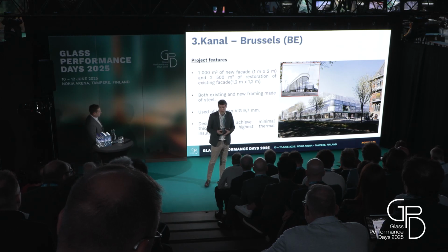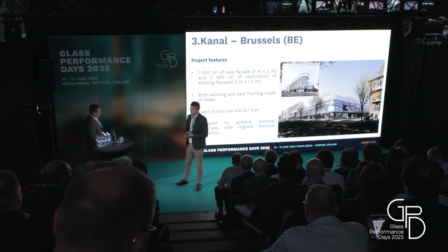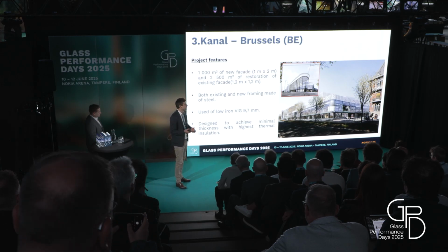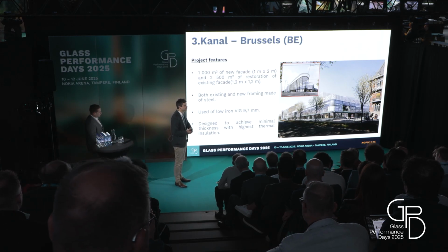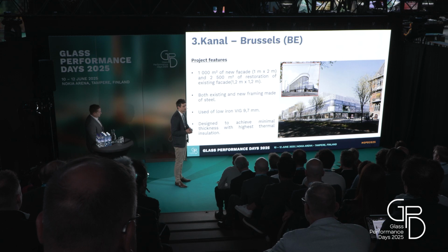And the purpose, so the VIG was meant to be installed for the basic value proposition, to achieve the highest thermal insulation with the minimal thickness in order for the VIG to fit in the existing frame.